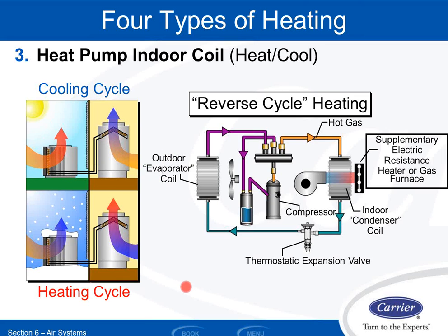So what a heat pump does is reverse the responsibilities of the evaporator and the condenser coils. So literally the coil inside my house, which used to be my evaporator coil, is now my condenser coil. And outside, my condenser coil is now my evaporator coil. It's like I took your furnace and your air conditioner, swapped them, put the furnace outside and the air conditioner inside, and then ran it, right? Well, it's too hard to physically move them, so I have a reversing valve, like I'm highlighting over here with my red highlighter mouse, and I reverse the flow of refrigerant instead of actually picking up the unit and bringing it inside.